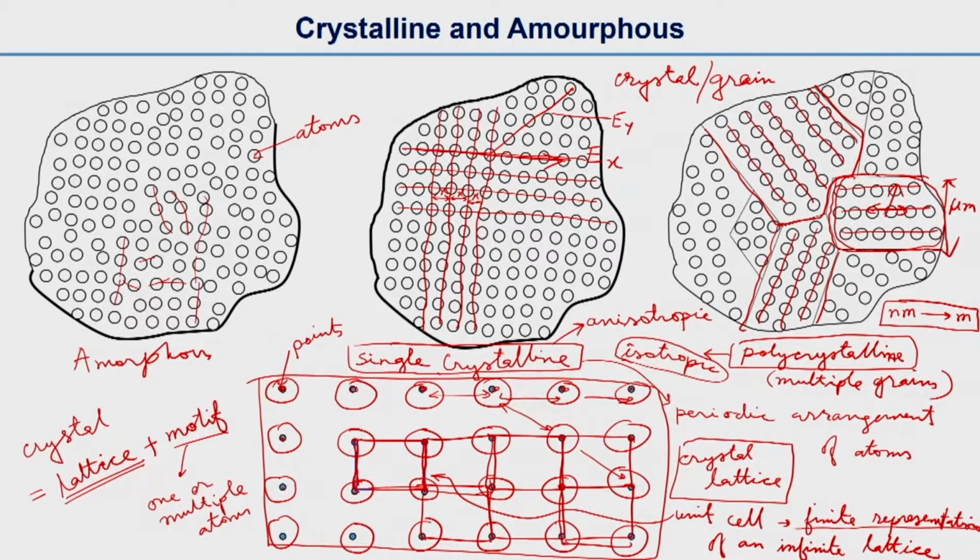But there are other cases of anisotropy that you can learn, like orthotropic material, transversely isotropic material, and also if you take a single crystal of other crystal systems, like single crystals of cubic, tetragonal, hexagonal, they all have different kinds of symmetries and their anisotropy is very different from each other. So they are not isotropic. If you take a single crystal, they are anisotropic, but their anisotropy is different. Cubic crystal is different than tetragonal is different than hexagonal.